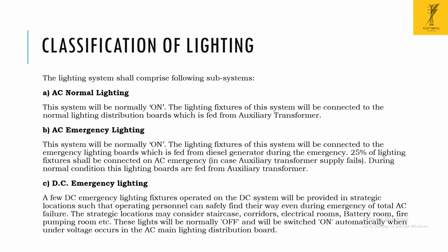A person using the space will mostly be in the office rooms or working area, so the lux level should be more in that area. Based on the lux levels and some other factors that we will see in the next slides, using these conditions we have to size the illumination for the substation as well as for the rooms.